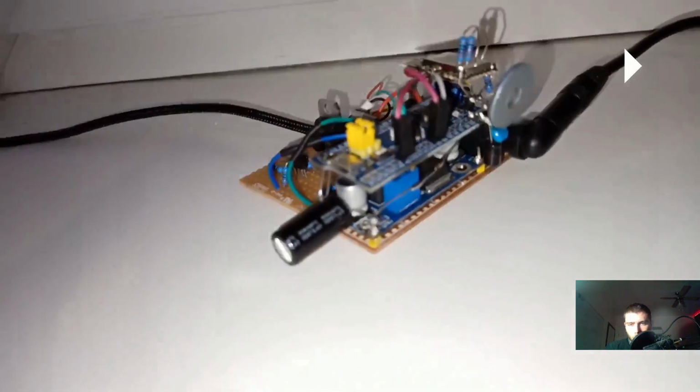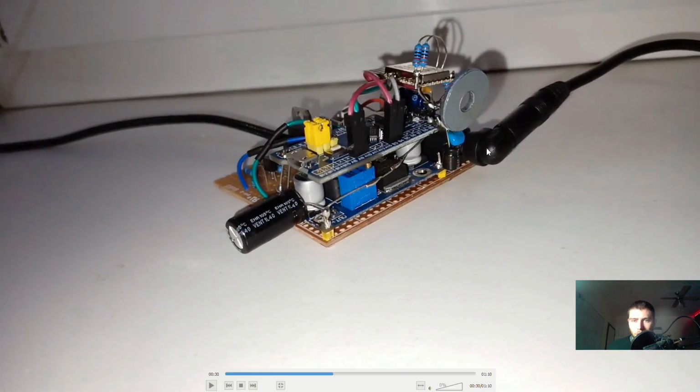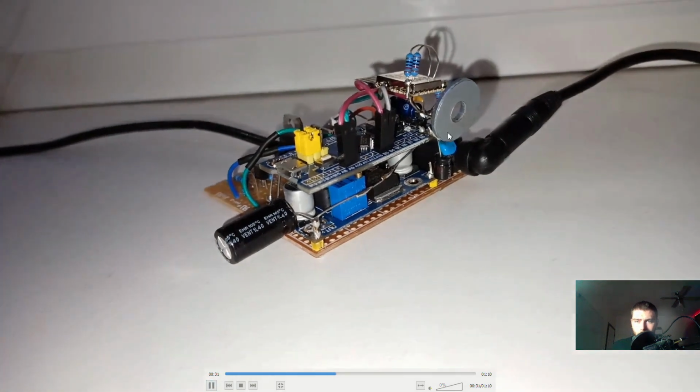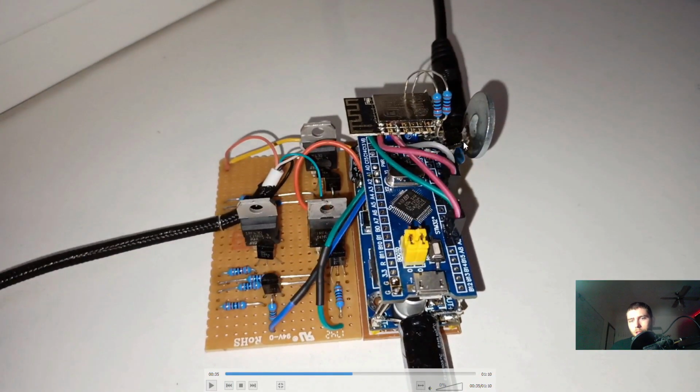And it is all powered via this cord, and it is powered by 12 volts. Before I connected all of this, I had to set the output of this step-down module to 5 volts. I'm using this step-down module, which has a coil and switching component, because it's very efficient and doesn't produce much heat. On the other hand, as you can see over here, I have a washer, and it is used as a cooler for this linear regulator, this LDO.